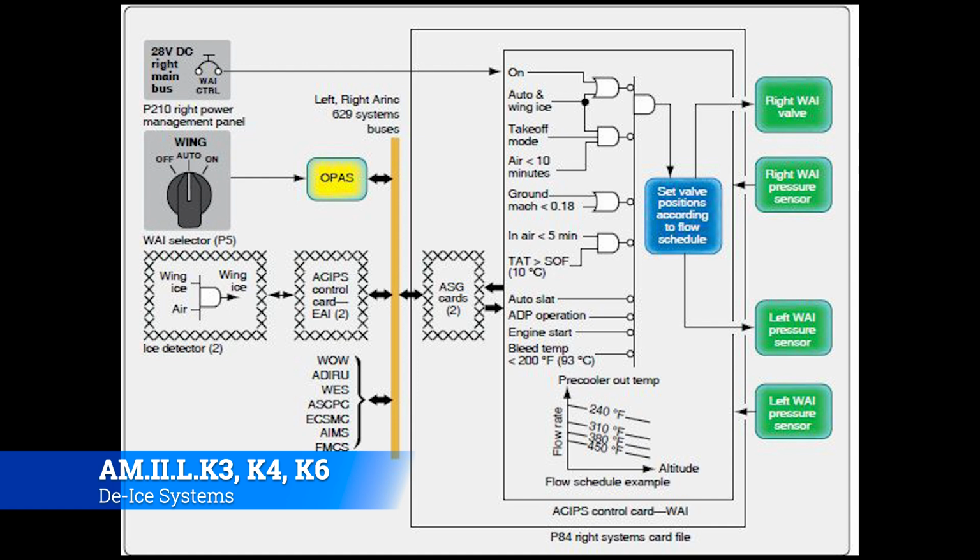It's a high demand time for the engine, so it basically shuts off all these little ancillary systems, that way the engine can use all of its power to get started and running, and not have to feed all these other systems until it gets up to a certain ENG bleed air temperature of less than 200 degrees.